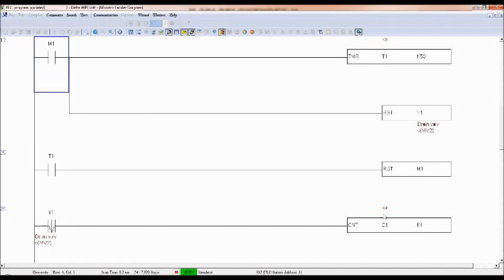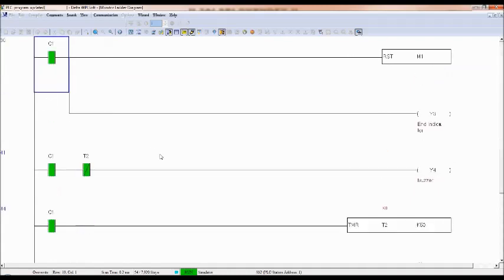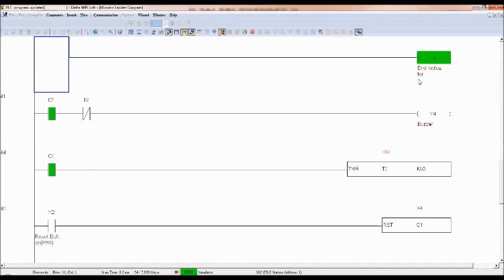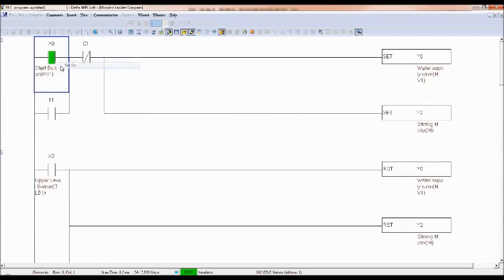Now again filling not started because counter is on. Okay. Now cycling process is completed, and the end indicator is on continuously. Actually buzzer was on for 5 seconds, but we couldn't see it. It's a very short time. Now end indicator continuously on. Even if you press start button, see here, even if you press start button, process will not start. So the only way is you have to reset the counter.